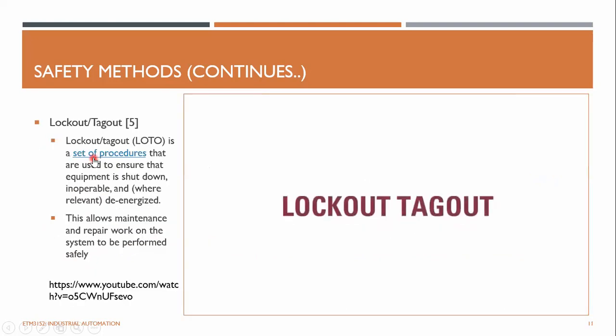And the last one is the lockout tagout. So when you go for replacement of anything, you put a lock and a tag, and that will prevent anyone from operating it. Say you go and do maintenance on a motor and you just disconnect your main contactor, right? Main power. Someone just realizes the system is not running and comes and presses that DOL, or direct online start, and that will literally kill you, because the person who is replacing the motor can be exposed to electrical shock.